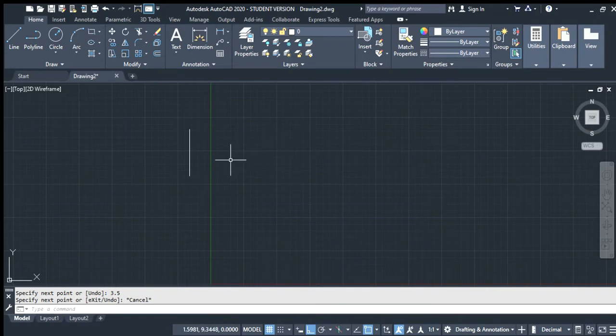I'm going to go ahead and hit escape, and then on this line we're going to start by drawing some concentric circles. So we'll hit C for circle, we'll go to the top. Now note there's measurements on these circles. Some of them have a little circle with a line through it. That means diameter. The ones that have an R is obviously radius. So you can tell why a radius with 1 is going to be greater than a diameter with 1.